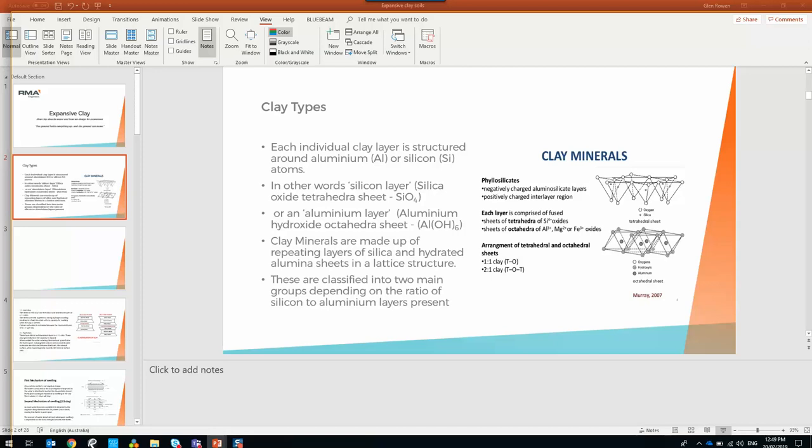Service trenches. Now, with raft slabs and void former suspended slabs, you're trying to stop moisture getting up, and then you're building service trenches, placing crusher dust fill against all your pipes, which has a permeability many times greater than the clay. So any surface water will just get in that trench and go each way all along the trench and end up underneath your building.